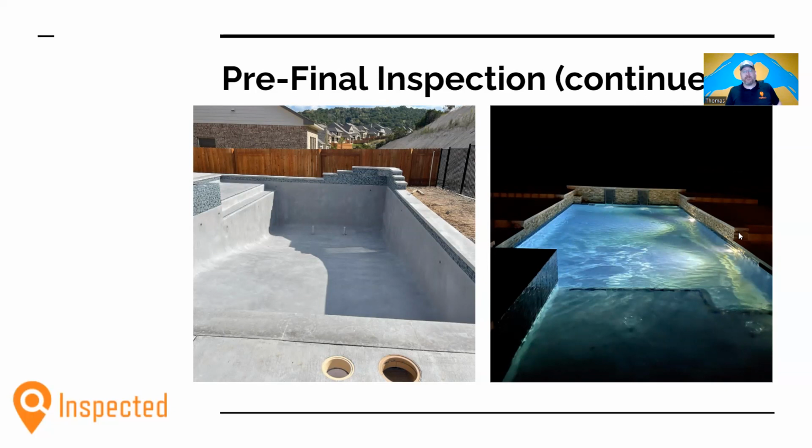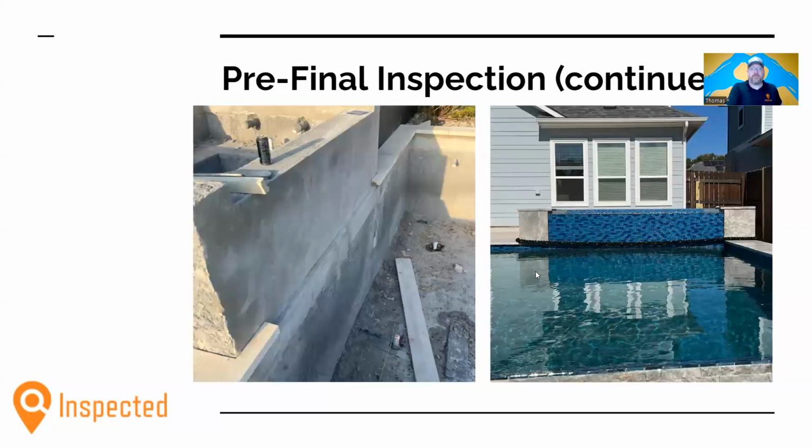Same on this pool on the right. It's got split face travertine, which is not a real functional handhold. And then a bench across the back, which should be okay if it's shallower than 20 inches. Then back on the left side, again, nothing to hold on to. And I assume this pool is deeper than 3'6". Again, you still have the issue with the spillover in the spa unless there's a bench in front of it. So consider that in your planning.